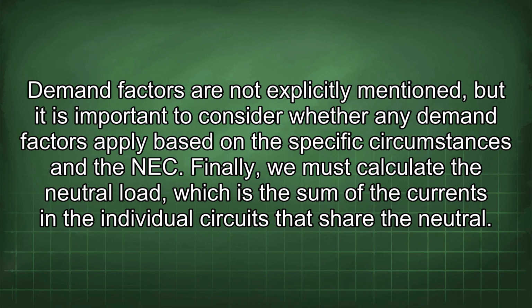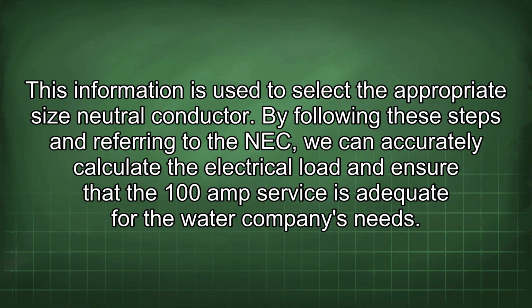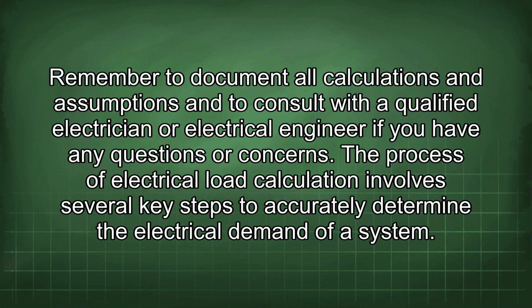Finally, we must calculate the neutral load, which is the sum of the currents in the individual circuits that share the neutral. This information is used to select the appropriate size neutral conductor. By following these steps and referring to the NEC, we can accurately calculate the electrical load and ensure that the 100 amp service is adequate for the water company's needs. Remember to document all calculations and assumptions and to consult with a qualified electrician or electrical engineer if you have